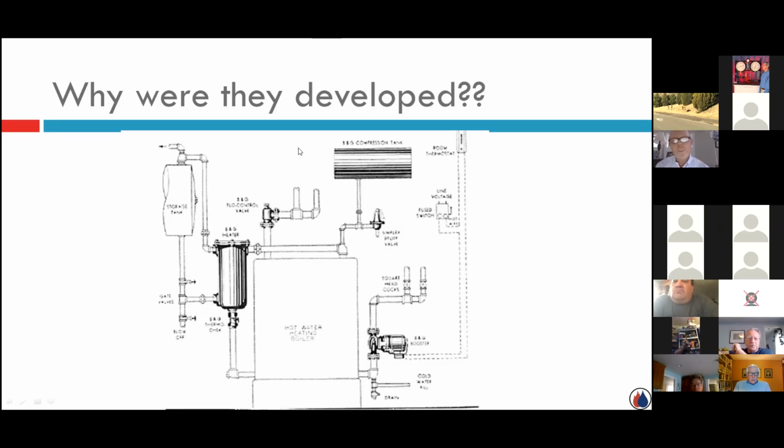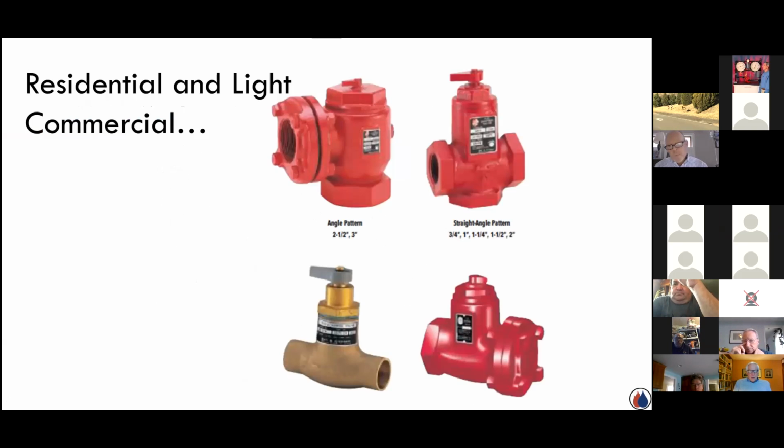Heat would go to cold. And so they quickly realized, okay, this is why this thing showed up. I don't want heat leaving this boiler unless that circulator over here turns on. Once he turns on and he creates that differential, it'll lift that weighted check out to the system. So a couple of pictures of some residential swing, they call these guys sweat checks, or they could be NPT threaded, SAs, they refer to these guys.